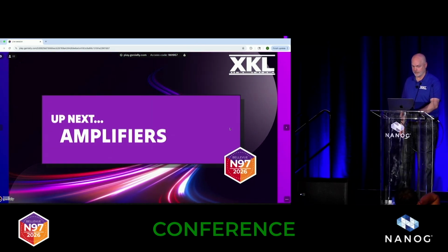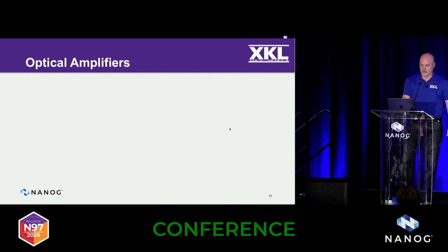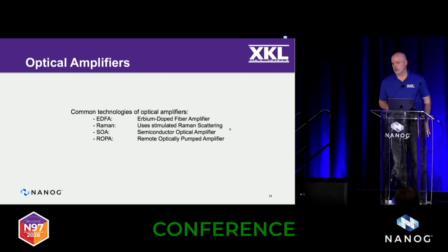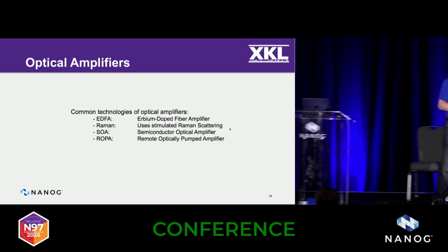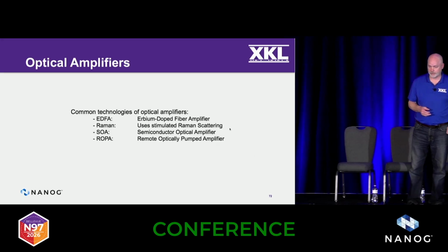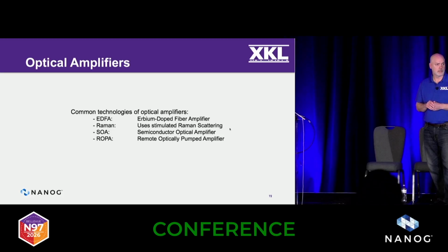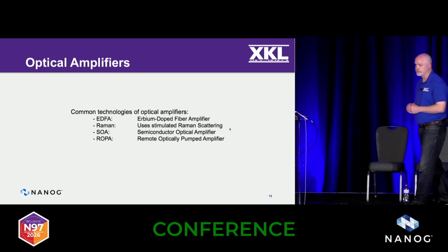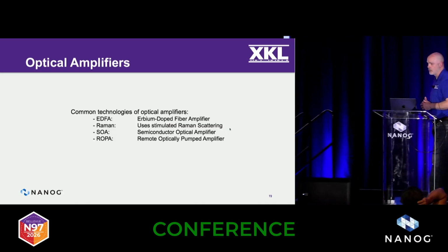All right, amplifiers. So the most common technologies, EDFA, erbium doped fiber amplifier. Raman uses the principle of Raman scattering. Talk about that. An SOA, a semiconductor optical amplifier, and a ROPA, a remotely optically pumped. So these are also in order of the most common.